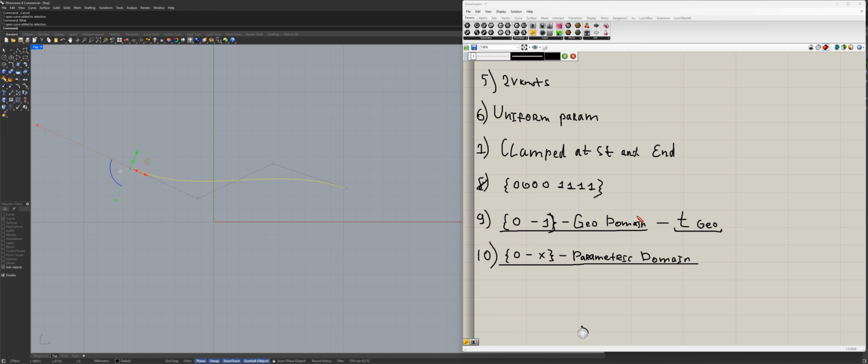The tighter the tolerance, the more calculations there are and the more t values there are; the looser the tolerance, the fewer t parameters there are. You don't have full control, you control it through the positional tolerance, because that's what it is.